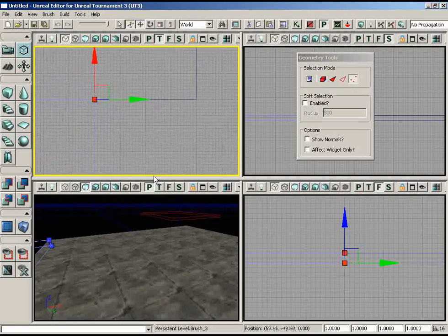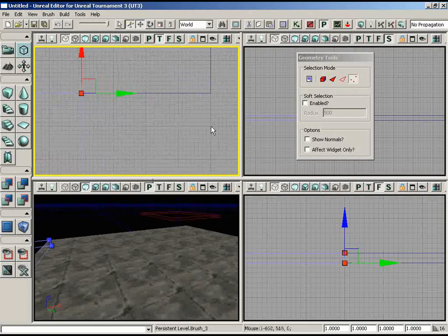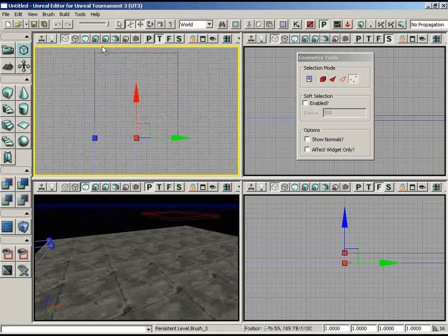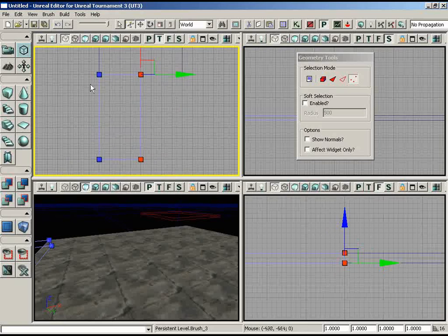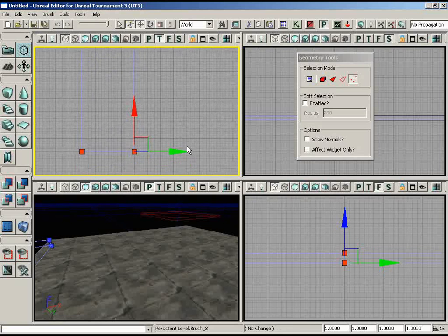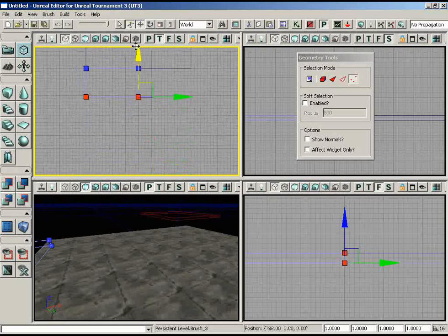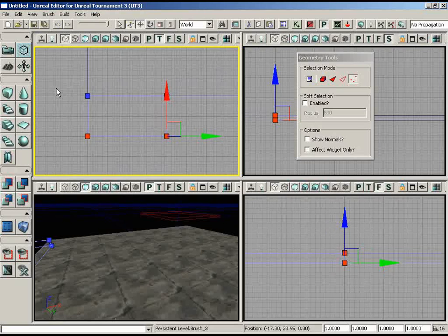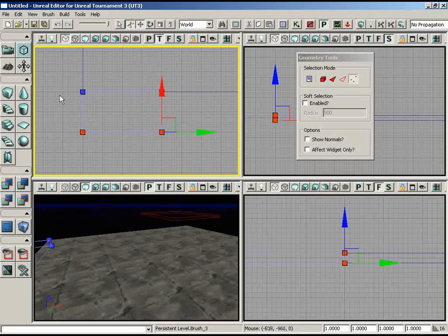If you want to measure to make sure, of course, you can always zoom in and use the middle click to drag out a measuring line if you're unsure about the measurements. But there is 512, so this little outcropping is going to be exactly half of the width of the room. So we'll edit those in. Now we'll drag these other vertices in somewhat about here. So I'm going by major grid lines here. I've got my drag grid set to 16. And looking at the more prominent darker lines, I'm out about 2 major grid spaces out.